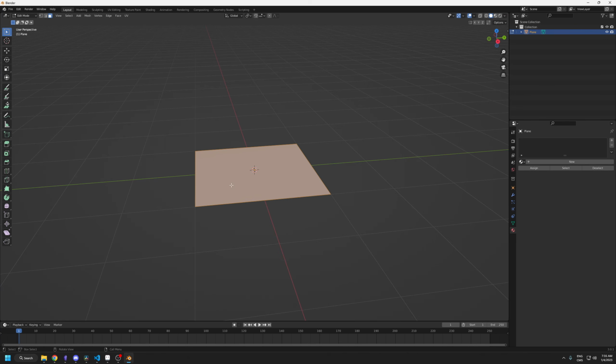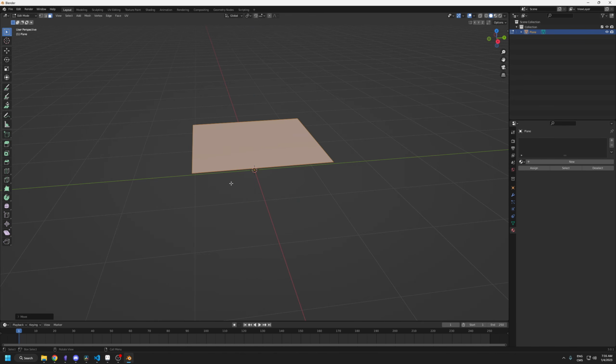Then I'll go in edit mode, select the face and do G to move and Z to lock the Z axis and type 0.5, then enter. That's going to be the basic ground tile. Then I'll right click and subdivide, so I'll have smaller faces to add the texture on. I decided that each square unit will be a 32 by 32 pixel texture.